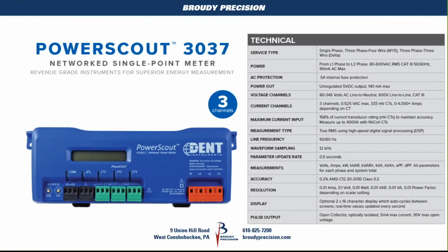You have your CT inputs, your current transformers that get wrapped around each phase, and then you have your voltage, line 1, line 2, and line 3 that's shown here on the left. That's the commonality that you'll see from meter to meter, because we need voltage and we need amperage to calculate kilowatts. All meters are going to contain the same sort of basic wired inputs.